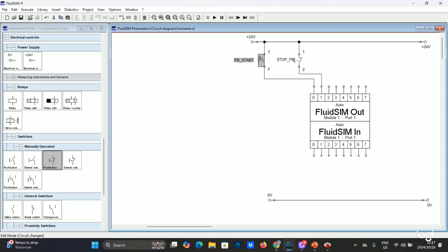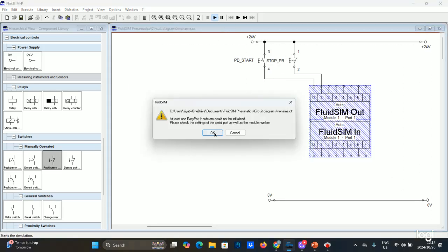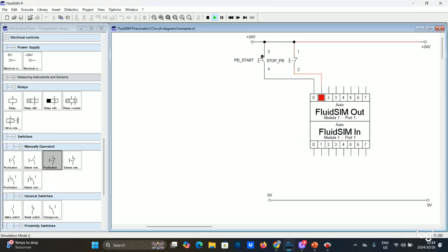While we're doing this, I want us to ensure that we don't make sloppy connections. Now if I can just demonstrate, as you can see, it's normally closed, so it's allowing power to flow through. But when pressed it cuts the power from continuing to flow. So this is your stop push button, it always has to be like this.